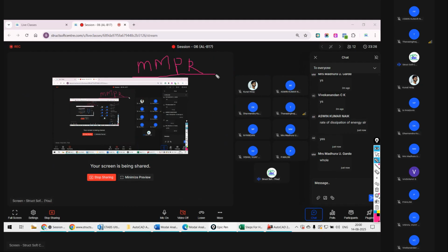सो सिस्मिक इवेंट में क्या होता है, बहुत जगह अभी आप देखेंगे सॉफ्ट स्टोरी कॉन्सेप्ट, it might be in your knowledge. Okay, it is very close to the concept of modal mass participation, otherwise they are slightly different. Okay, but in that soft story concept, the failure will be what, lower floor of the structure is less stiff and upper floor is more stiff. There is a concept of stiffness. तो नीचे का फ्लोर कम स्टिफ होता है, ऊपर का फ्लोर ज्यादा स्टिफ होता है. तो बिल्डिंग ऊपर का एज इट इज होता है, नीचे का कॉलम फेल हो जाता है. That is the concept of the soft story.